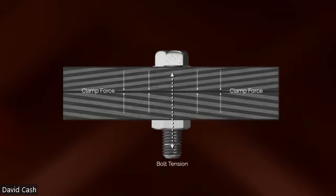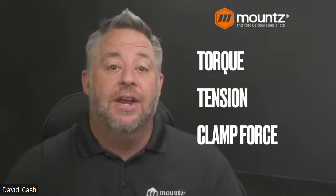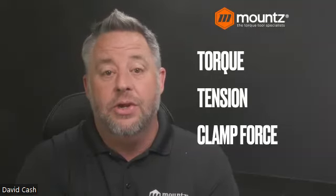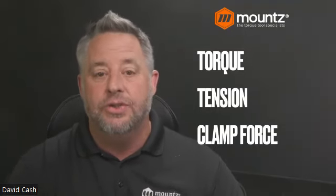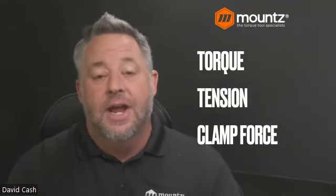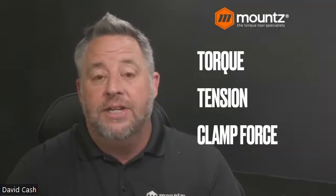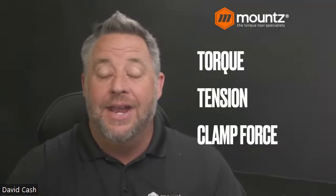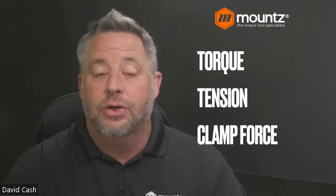If we think about the bolt itself as a spring, as we stretch that spring it provides more tension. So the torque that we use gives us tension, which provides us with the clamp force, and that's why we use torque. There are other ways to create tension in a fastener, but they really don't work that well in an application or an assembly type of process. And so that's why we use torque to do that.